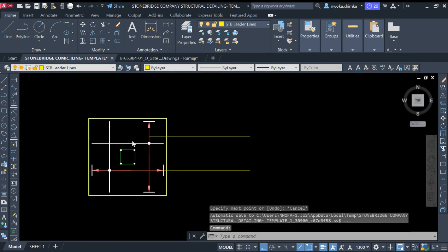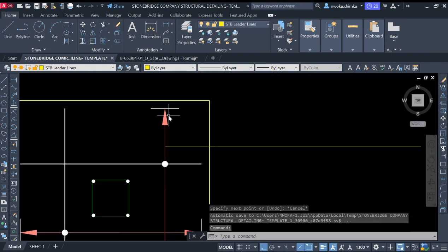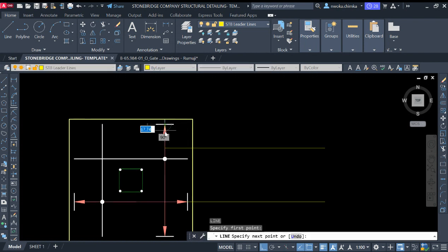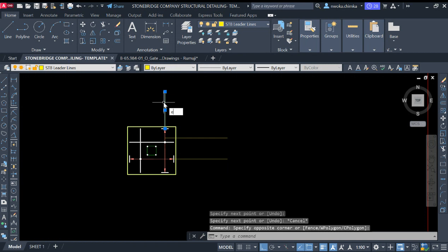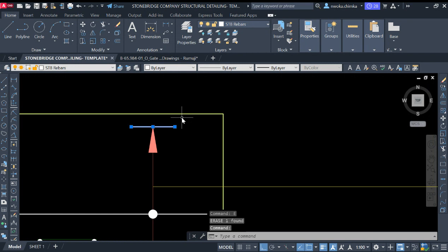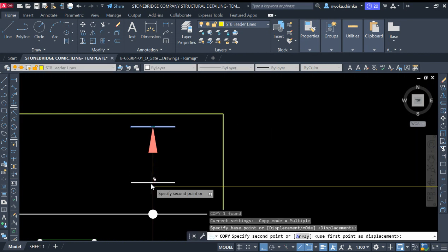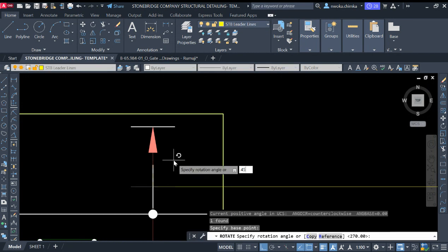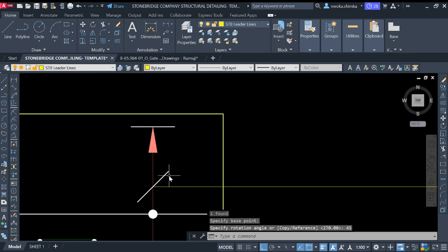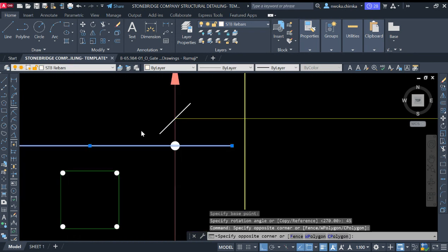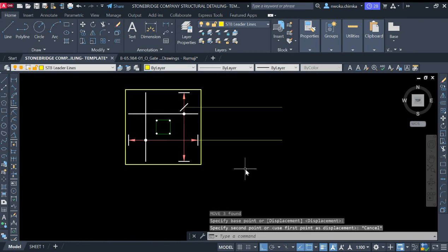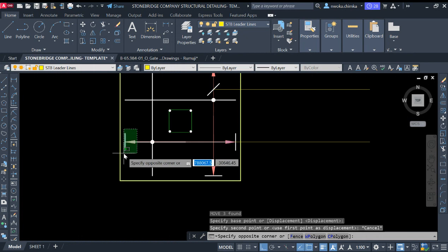Now, because we have done this right now, since we didn't take this point from this arrow here, we want to number all our reinforcement from this direction and not to show it this way. Although most people can show it this way if you want, but just to make sure everything is well aligned, I'm using one side direction to number my callouts. So I'll just copy this right now, copy CP, and then copy it to this point to show that I'm pointing this. Then change this rotation right now to angle 45, and enter. You can see that. So right now I will now move this one downward, just to avoid confusion, or leave this here and move this downward a bit, as you can see right now.